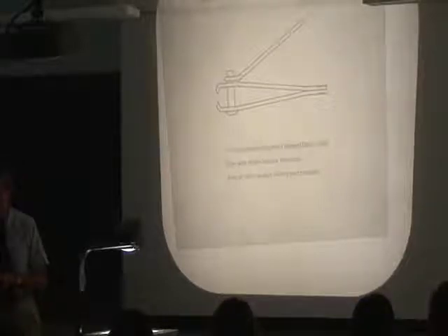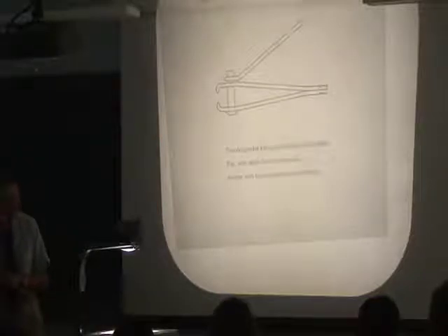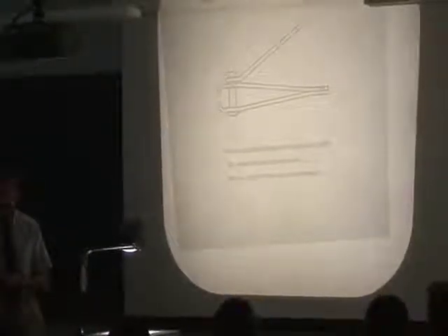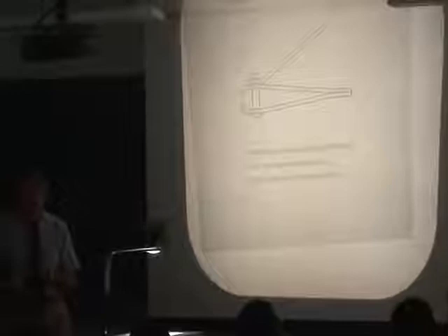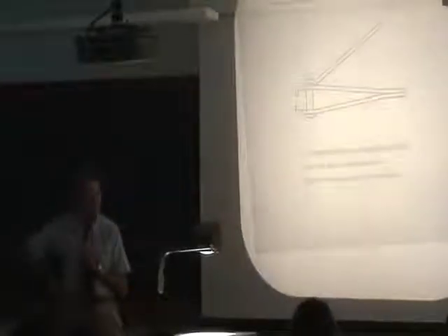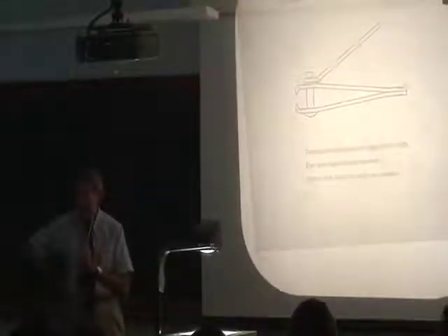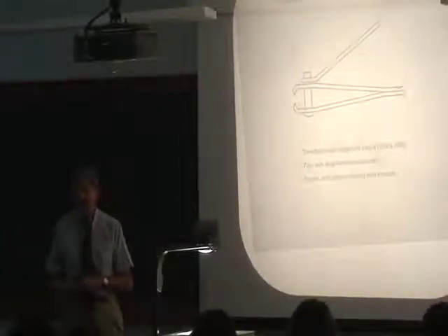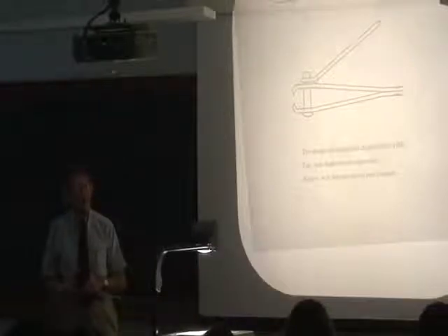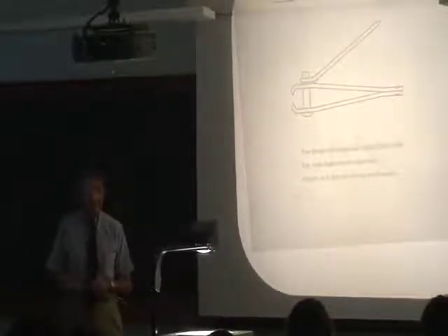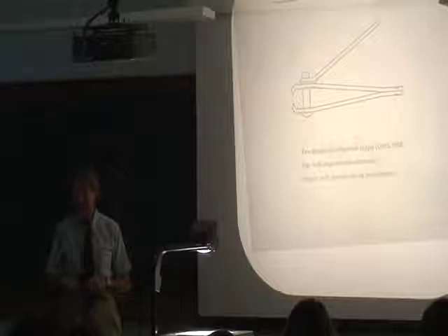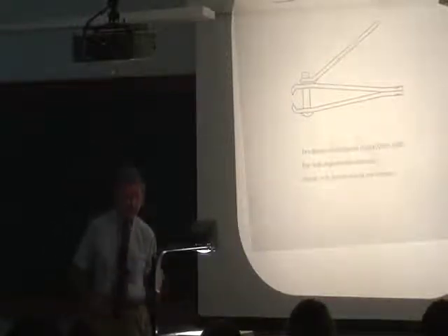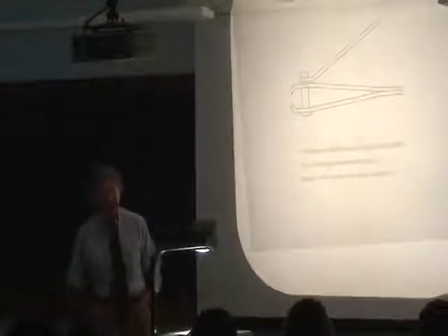Think of the door of a car. And just sometime when you are sitting around musing, write down mentally or on paper the various things that the door of a car does. And you'll have quite a long list. It adds structural strength, it keeps the rain out, it adds aesthetics, and so on. Those are the easy ones. Let me give you one you probably would not think of. It's a link in the electrical ground chain of the car. See, and there are lots of things like that. So it's function sharing which makes mechanical design so challenging.